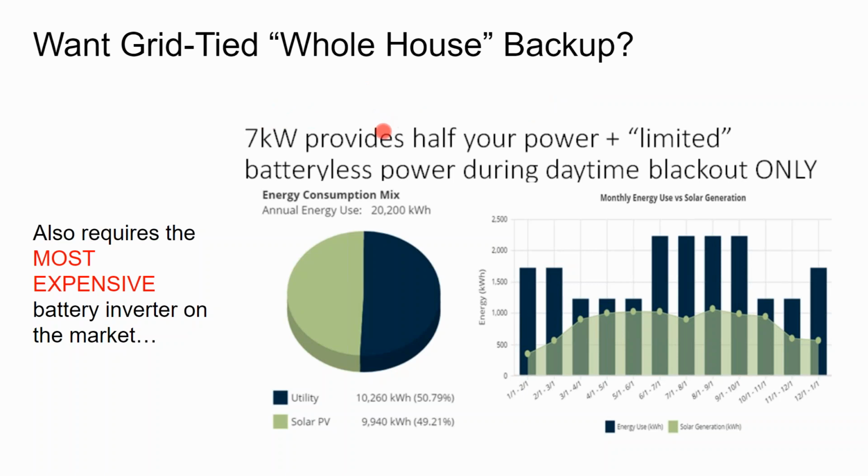There is an inverter called SMA that makes a dedicated power outlet that will turn on during the day without batteries and just run off the solar array, but they substantially curtail the amount of power you can get out of that. It's only about 2 kilowatts.